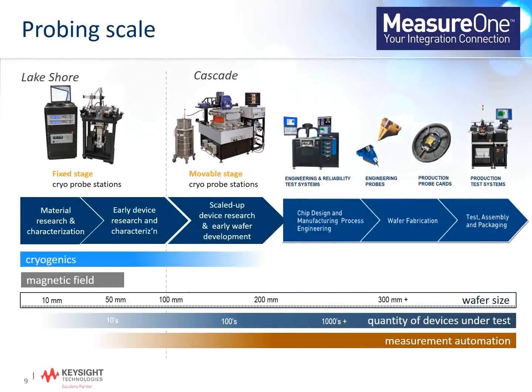Lakeshore cryogenic probe stations are manual probe stations designed around doing research-grade characterization. In a manual probe station, you independently move each of the electrical probes using a micro-manipulated stage to each individual device pad. So these research-level measurements are really built around few device characterization. This is what you encounter for research-level characterization, where you're trying to tune a material property or tune an architecture. So we're not making thousands of devices, we're making few devices, and we want to characterize those devices typically over temperature.